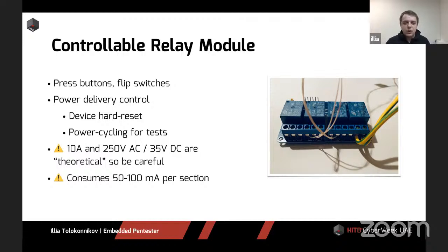This kind of power control, we started using it for power cycling tests. So some test stands just run like 10,000 power cycles and see if the device survives that. It's a good test to measure the reliability of your device against this kind of voltage spikes. The other thing is, let's say you're running a critical process on your device, some kind of an OTA update or whatever, and you test whether the device survives a power cycle somewhere in the middle. Let's say you start writing on the flash, and then power cycle, and then power cycle back, and see if the device boots.